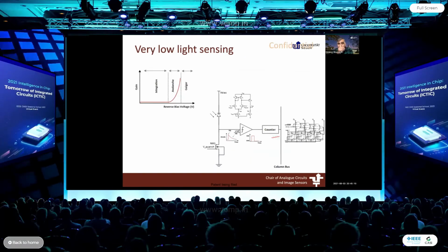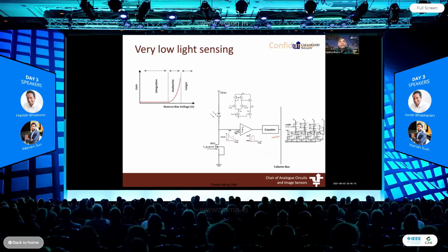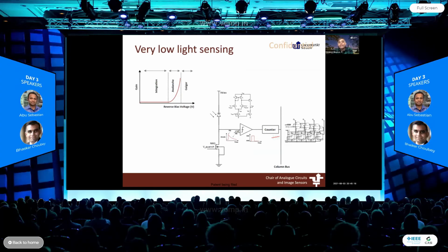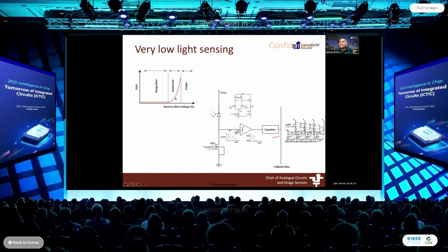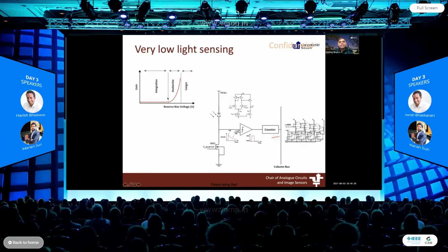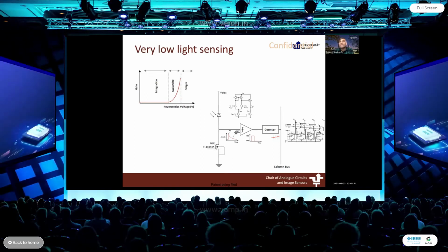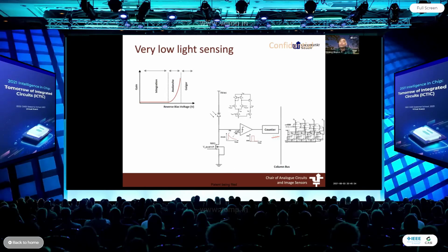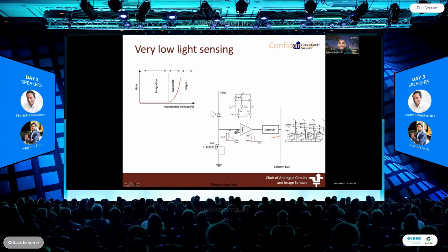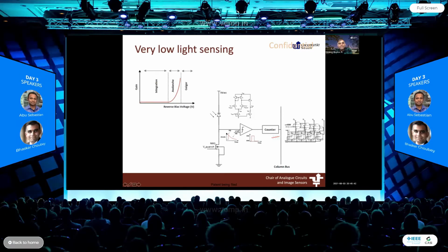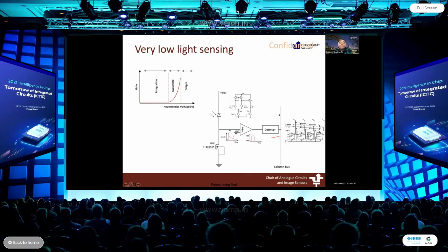The other thing which we can do is, another example of how we end up designing cameras with loads of transistors and hence not get very high resolution is single photon avalanche detectors. I mean, here we are trying to measure very, very small amount of light. So rather than measuring light just as a direct photon generating electron hole pair, we take the pixel into the avalanche region where one photon leads to a large number of electron hole pairs. For these circuits, we generally need a counter. We need a comparator. So as you can see, we have got about 50 odd transistors in one pixel.